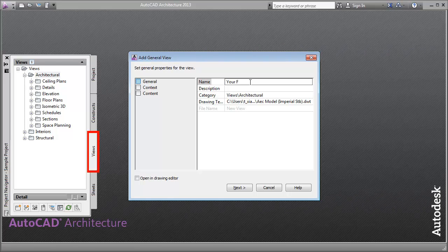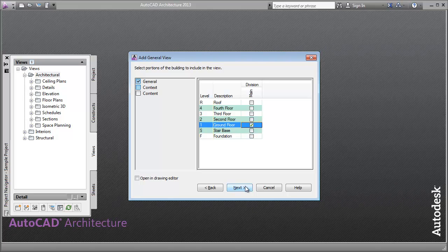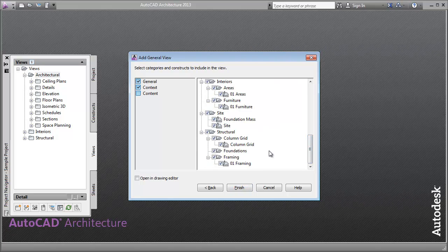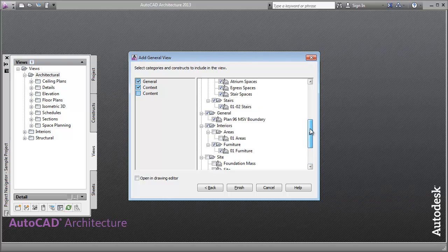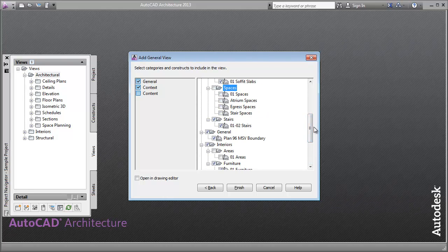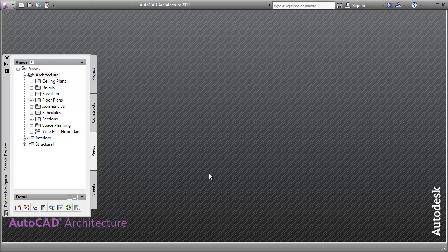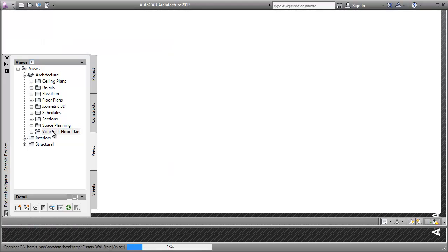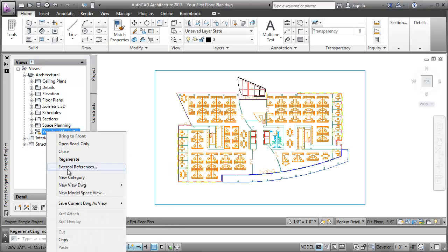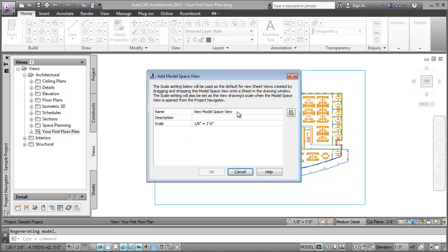The Views tab allows you to specify in architectural terms which base drawing files or constructs to automatically gather up to create the desired plan. For example, creating a view of the first floor is a very easy task. Simply specify the desired level, and the Project Navigator will walk you through its creation, automatically filtering out drawings belonging to other floors. The appropriate base drawings are automatically X-referenced to the newly created floor plan view, eliminating the traditional method of attaching these files manually.